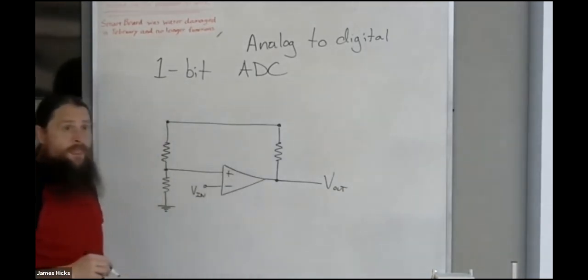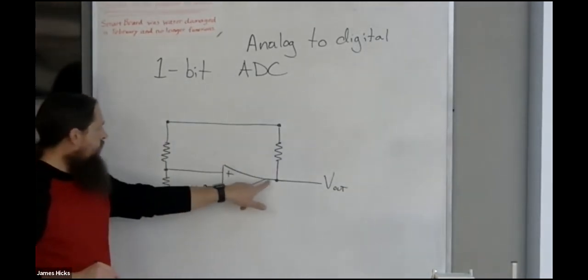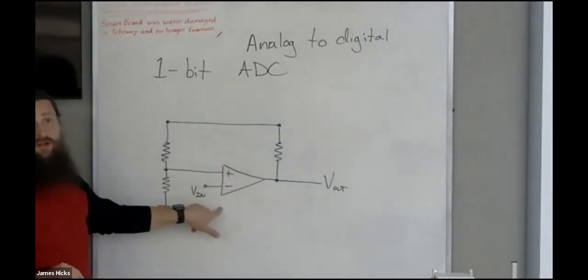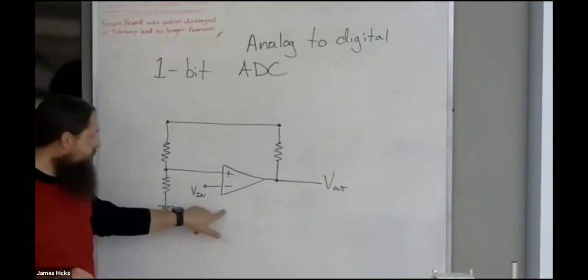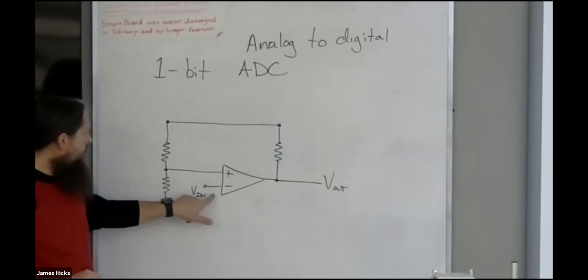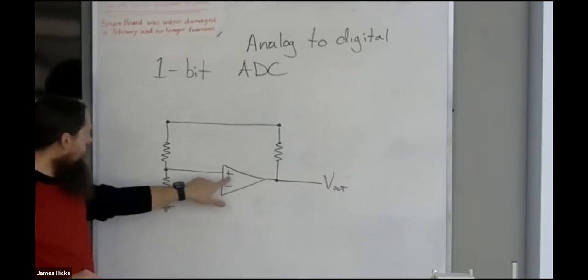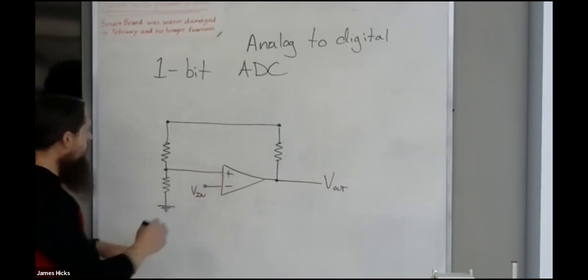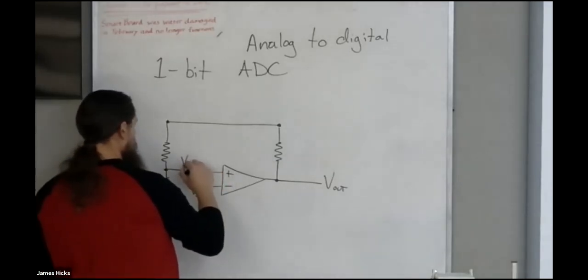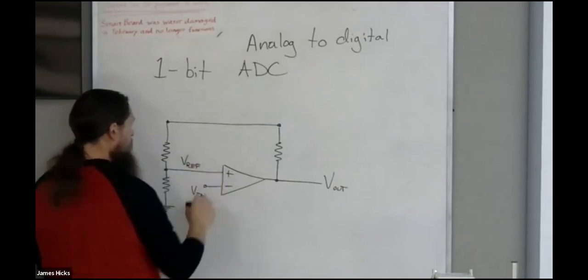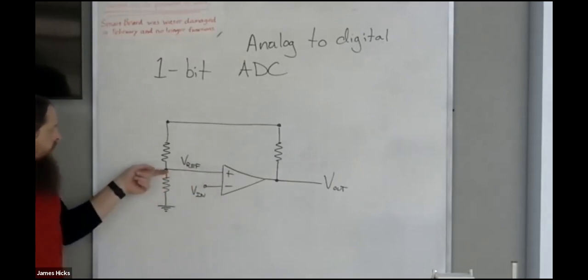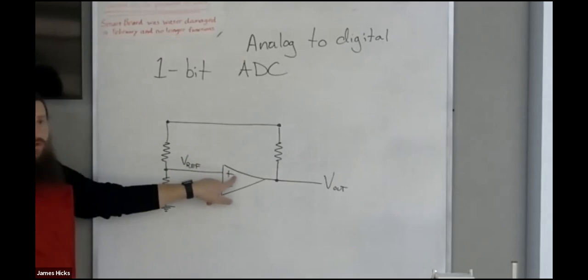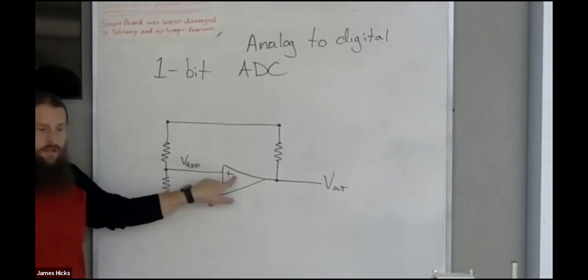All right. This triangle here, that is my op amp. It's being used as a comparator in this case, comparing my input signal to this reference voltage that's coming in to the non-inverting input. So for the comparator, the reference input is to the non-inverting op amp.